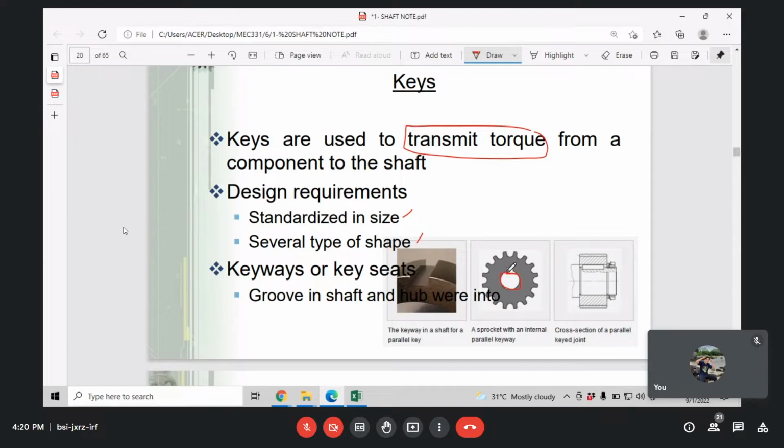Then they have some groove, the groove dia here. So when we have a key, then they have a lock here. There is a lock, so it will not move. It will fit properly. It will not wobble here. Normally the groove and the key must have some tolerance, but it will not move until it wobbles, okay. It will sit well and make sure there is no vibration or gap between the gear and also the shaft.